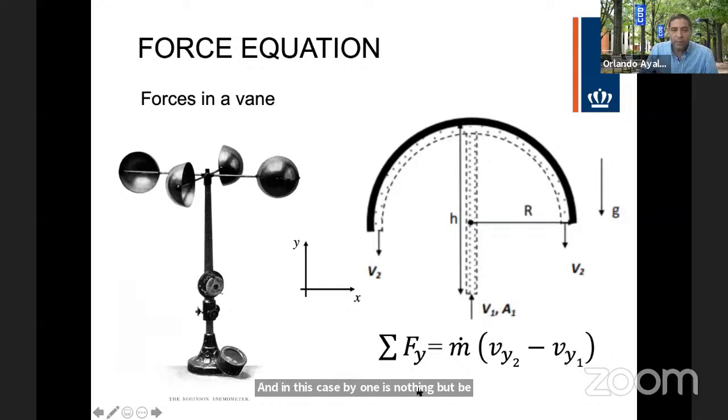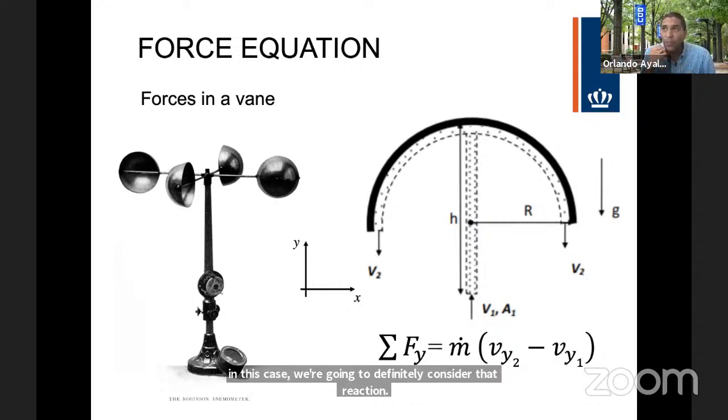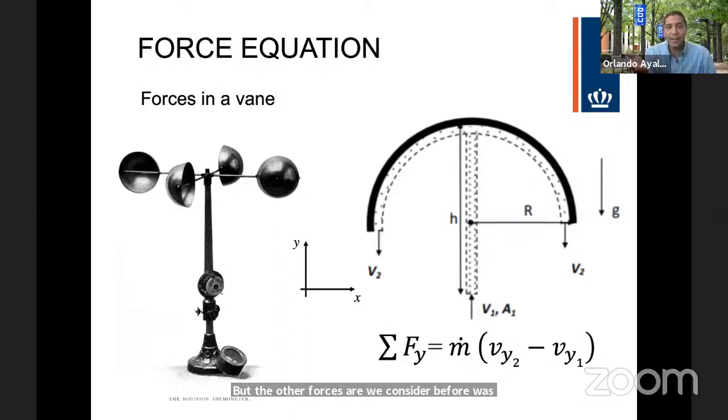The other thing to identify is the forces. Before, we saw that every time there is contact between the fluid and a solid, there is a reaction, so the reaction force is there. In this case, we're definitely going to consider that reaction. The other forces we considered before were the weight and the pressure. But in this case, the pressure is the same, because this is open to the atmosphere, and the pressure in the atmosphere is constant, so there is no pressure change.